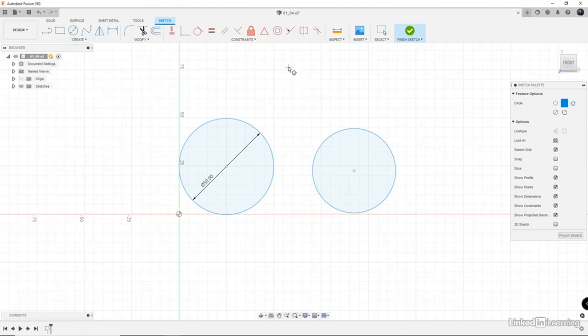So this one is really cool because you specify 2 points and then you specify the diameter, and it will always intersect those 2 points. So I use this a lot when I have two pieces of lines or two geometries that I need to connect, and I want to have some control over that radius, that diameter of that circle. So I'll have a line segment on those 2 points or some sort of geometry, and then this is kind of like the connector, and I kind of get a feel for what I want. Really handy tool. I don't use it very often, but it's very handy when you need it.